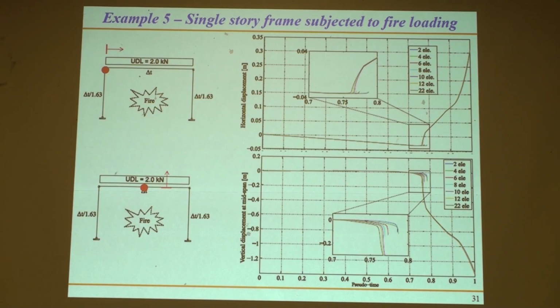So again, looking at mesh convergence, the results are not very visible, but I'd like to point out that you do get some effects of what can be called localization. More than that, when you start initially with few elements, we couldn't even pass this stage, so there were convergence problems with fewer elements.